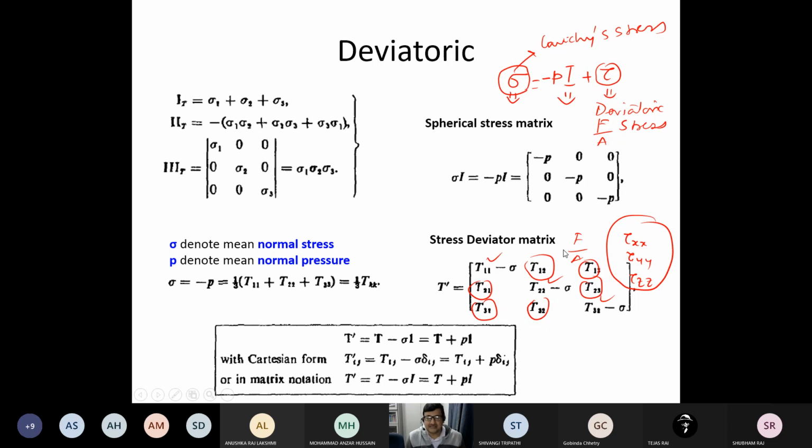As I am changing things in the system, as I am putting force, I am expecting that all these stresses are going to change. This is not going to change. This will be a fundamental property of the system. This I have identified from the stress tensor and its eigenvalue. This scalar has been identified when I did an eigenvalue analysis; from there I have found the invariant, and from there I have identified this property. Is that clear?